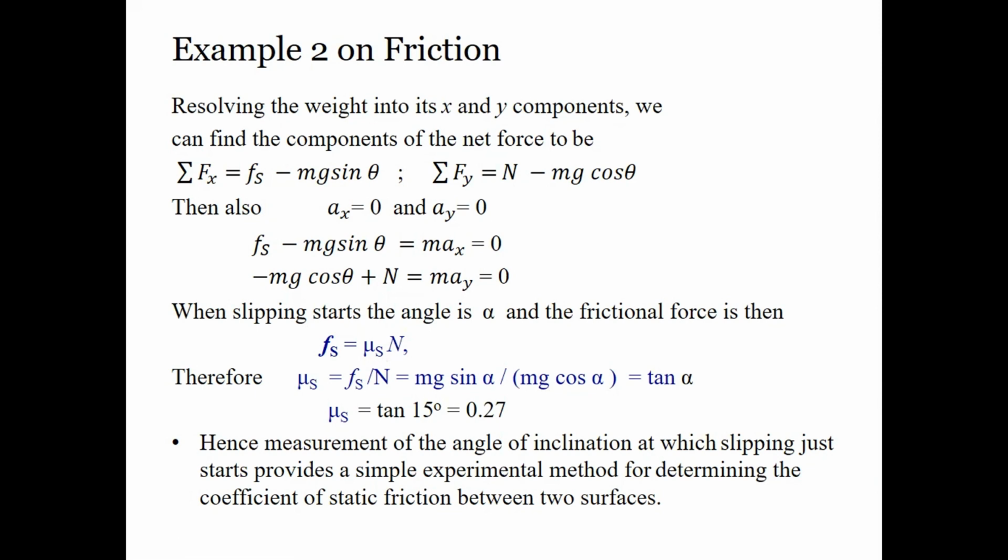Then we can find mu s as the ratio of the static friction to the normal force, and substituting these values, we find that this becomes tangent theta, the tangent of the angle.